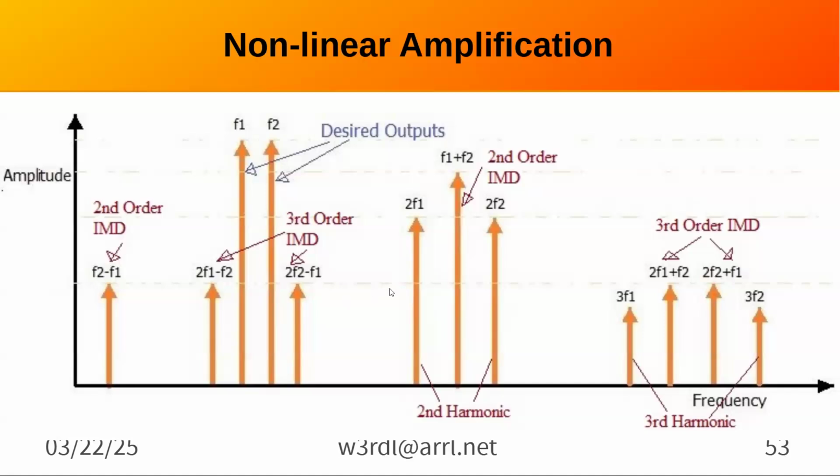Did you understand this chart since you were going to talk about it? No, no. Okay, I'll try. There's no question yet. It comes later, not today. What's the chart? Intermodulation products. F1 and F2 are your two signals, your fundamentals you care about. We won't talk about how they were generated. And then what all the intermodulation products would be for those. And if you notice, you've got two sets of third order, one way up here and one down here right next to it.